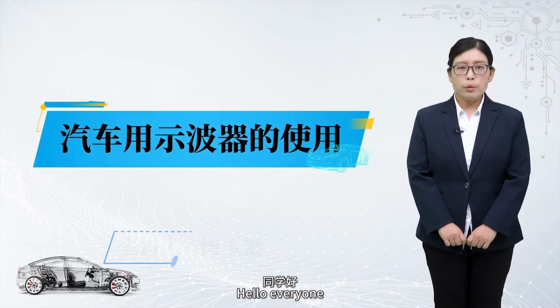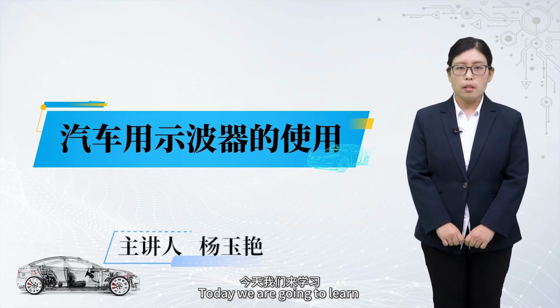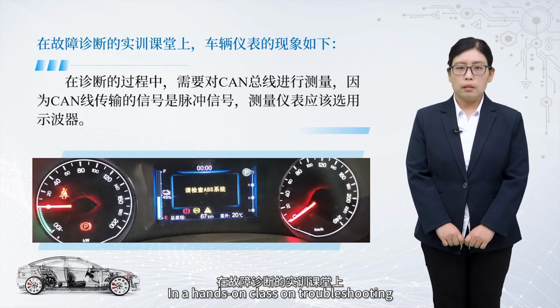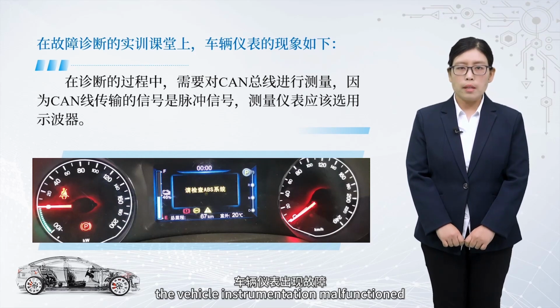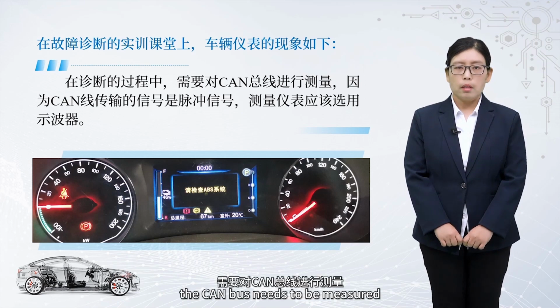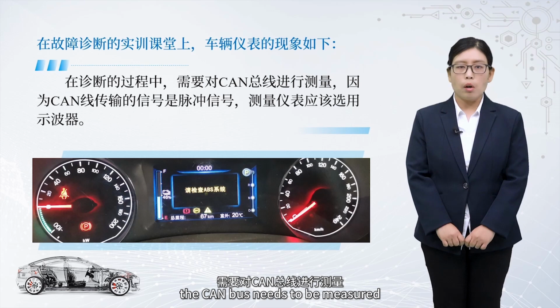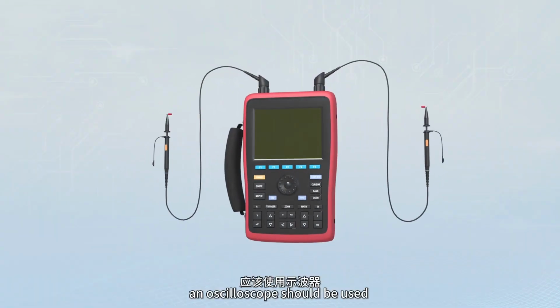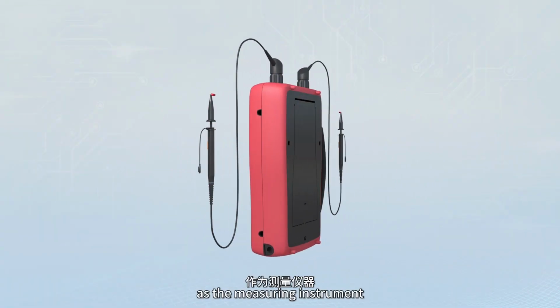Hello everyone! Today we are going to learn the use of automotive oscilloscopes. In a hands-on class on troubleshooting, the vehicle instrumentation malfunctioned as shown below. During the diagnostic process, the CAN bus needs to be measured because the CAN line transmits pulsed signals. An oscilloscope should be used as the measuring instrument.